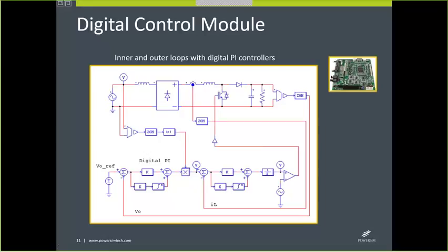If we wanted to, each one of these zero-order holds operates at its own defined speed. So you can define them to be all the same, or you could define some to be faster than the others. It's all up to you to decide and determine the appropriate speeds for these blocks to work at, and you can see the effects if you define them incorrectly. So you can have inner loops and outer loops that work at different speeds, essentially is what I'm trying to say.